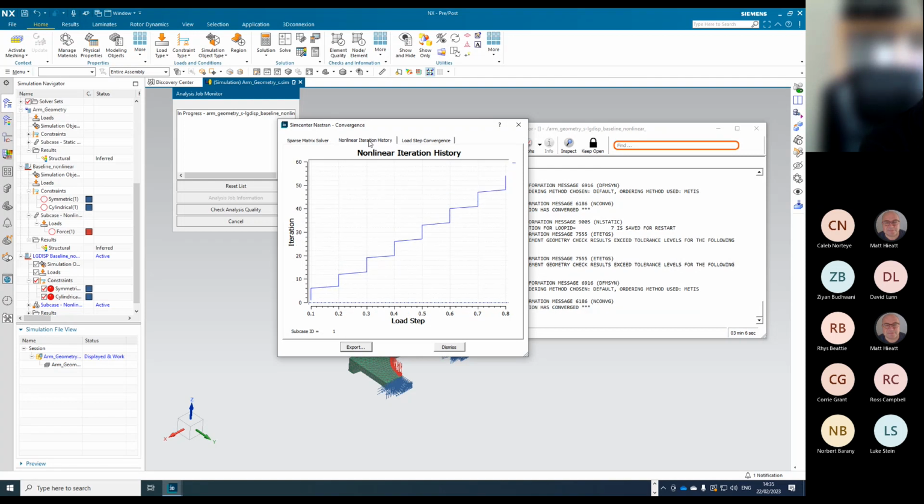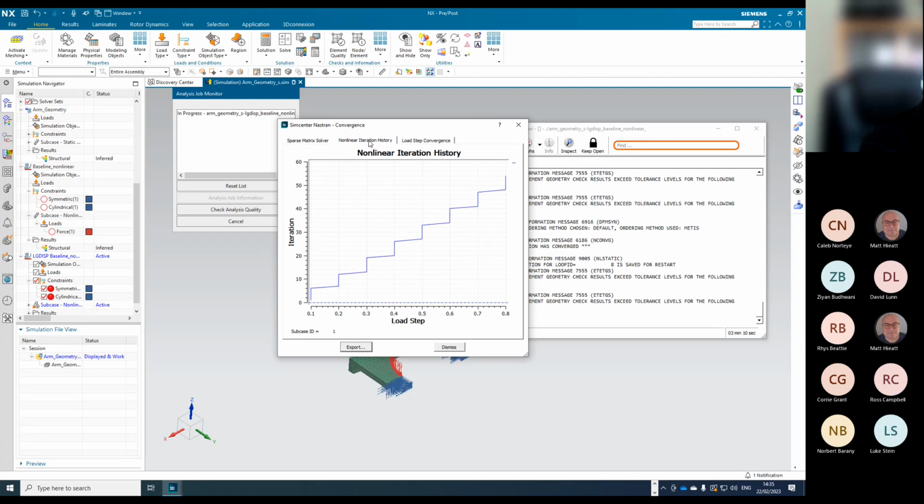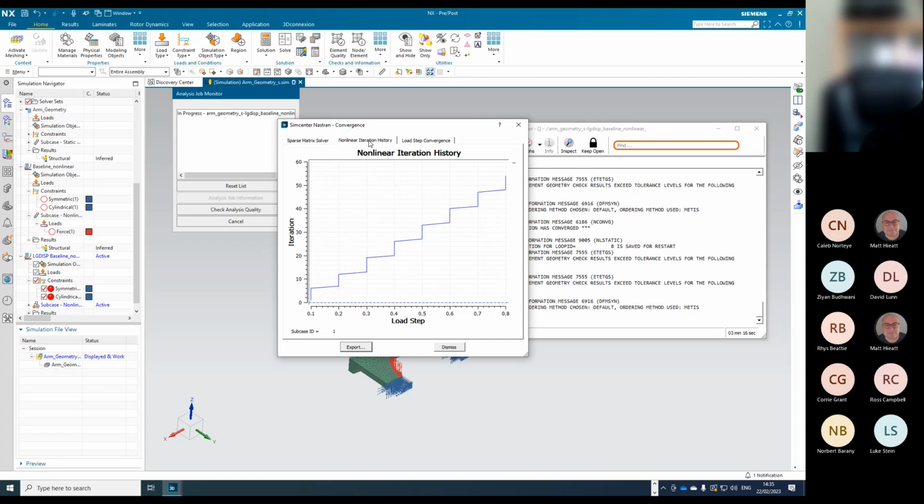You'd maybe use this method if you wanted to look at nonlinear buckling. So you might want to progressively step the load on and see at what point it becomes geometry nonlinear, at what point it starts to buckle. And I actually did a buckling analysis on this bracket, which I was going to include in the session, but I decided not to put it in.